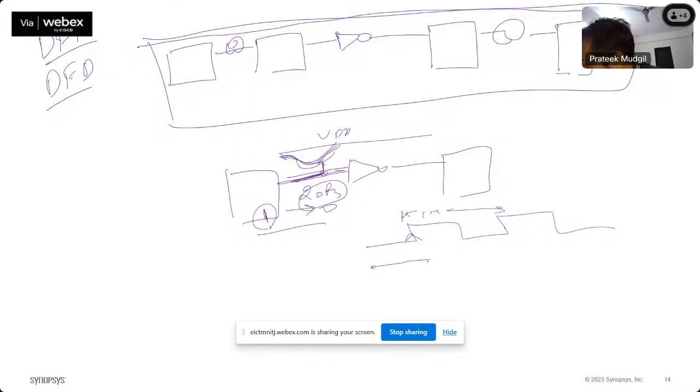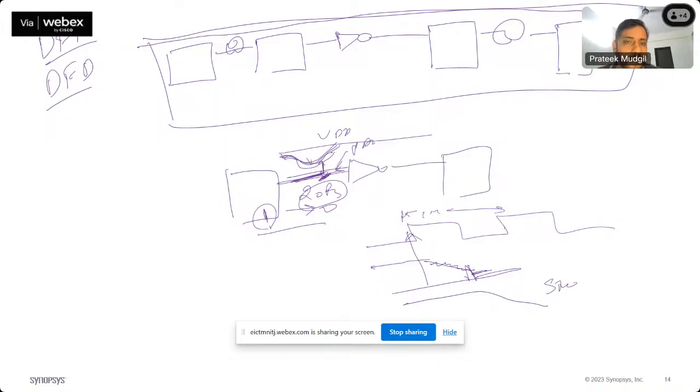So when data is going from 1 to 0, the real data will go low here, right? Transition here, this charges, and we get the data low here. This is the real expectation. What happened, right? The VDD line passed nearby, and this line, by magnetic interference, or you can say disturbances, I'm not deep into this characterization, I'm an RTL designer, but what I know is that there is a disturbance due to that, which can pull this line towards VDD, right? So it is possible that it is shorted and can never go low. This is called a stuck fault. There is a terminology in ATPG scan chain, we say stuck fault, right? So when a stuck fault is there, this is connected to 1 and it will never go 0, right?